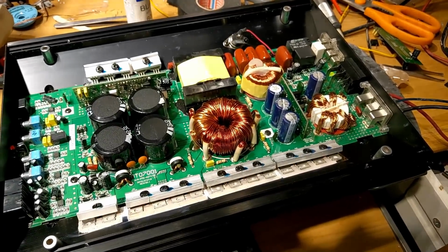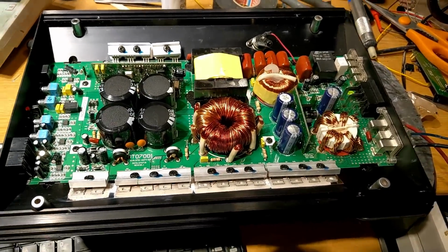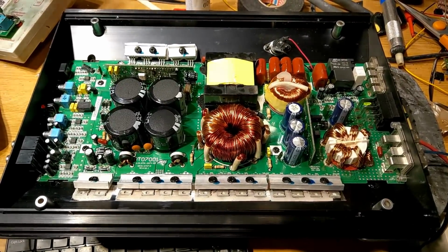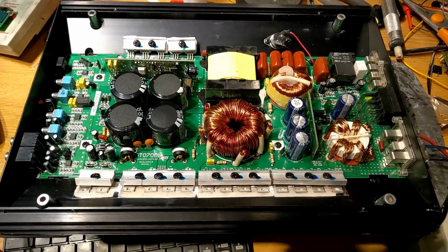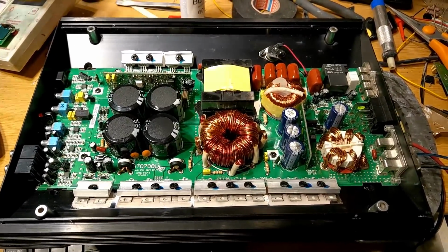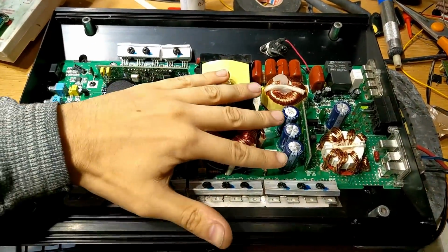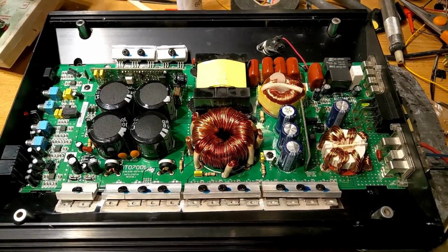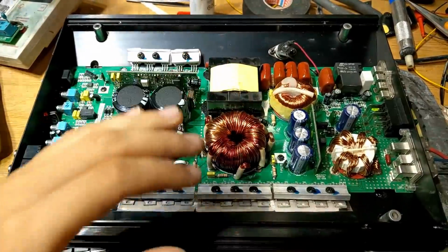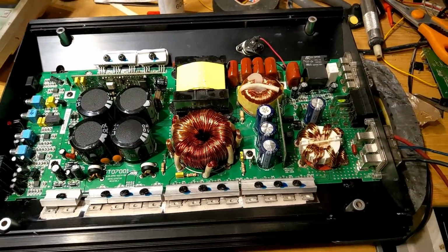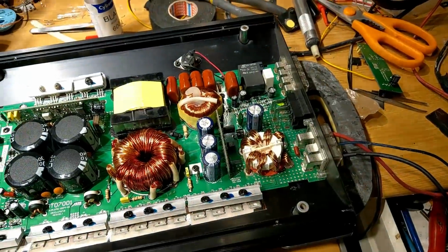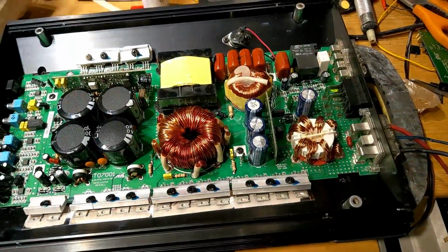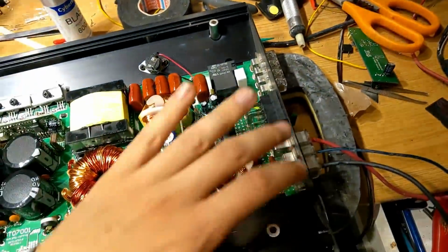So this here is a common issue I tend to find in these JBL GTO amplifiers. This is a GTO 7001, and it's common also in the 14001 and probably in the 24001 as well. If these amplifiers are left to sit for a long time without being powered up or connected to a 12 volt supply, these power supply capacitors, I don't think are particularly high quality, and the issue you'll find is after being sat for a long time, these capacitors will become critically empty, and when you try to connect power back to the power terminals here, the fuses will just continuously blow, and eventually if you keep trying that, these capacitors will explode.